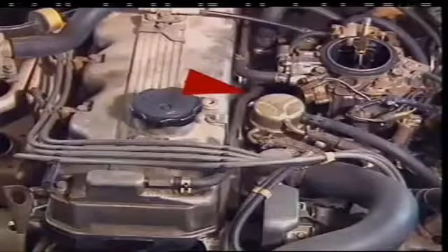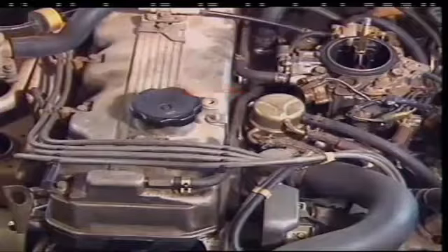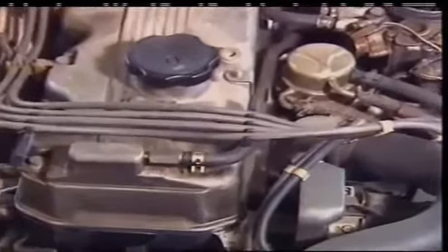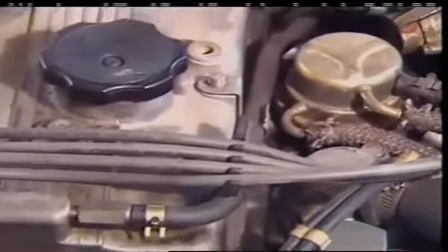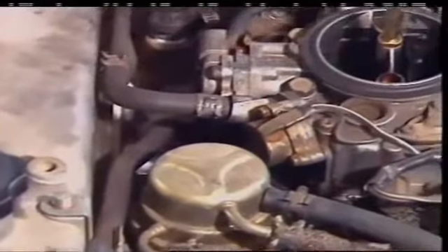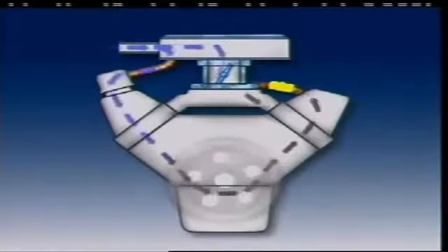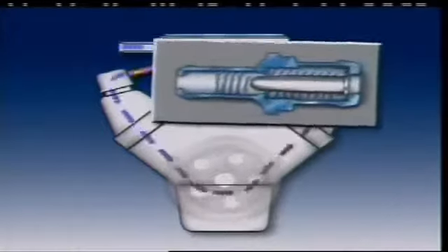Modern vehicles are required to direct crankcase breather gases and vapors back into the inlet system to be burned. A common method of doing this is called positive crankcase ventilation, or PCV. A valve called a PCV valve regulates gas flow between the crankcase and the inlet manifold. It is controlled by the pressure in the manifold.